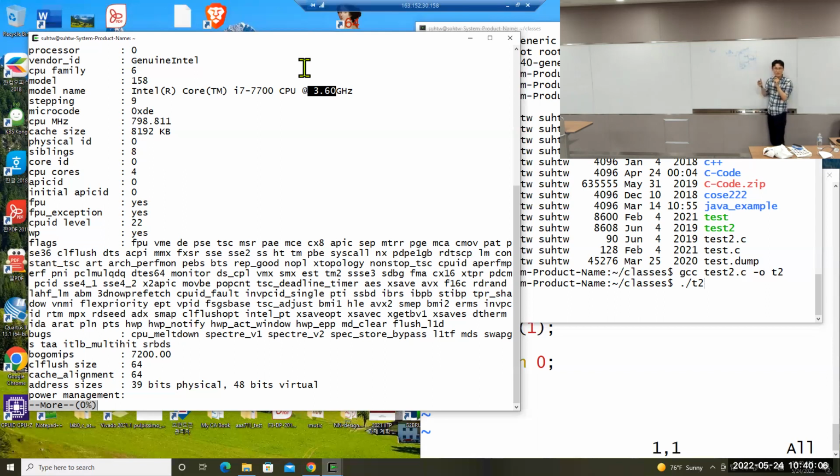The Cortex A9, the CPU we are studying, is based on a 32-bit architecture. That is why each register is 32 bits in size: R0 is 32-bit, R1 is 32-bit. In a 64-bit machine, each register is 64-bit, and the CPU reads from the register file and supplies that data into the ALU.